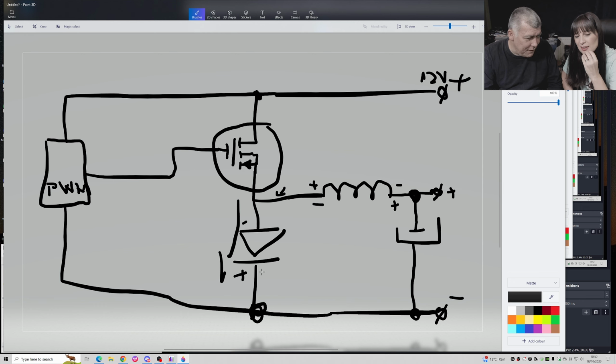So you have to put something else. When the coil is bouncing, we charge it with plus and minus, and it will bounce back with minus and plus. The minus will not flow in this direction through the diode. To have the minus flowing in this direction, the diode has to be turned around, opposite.